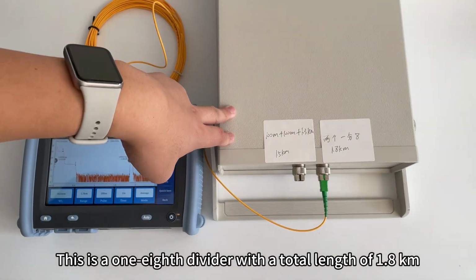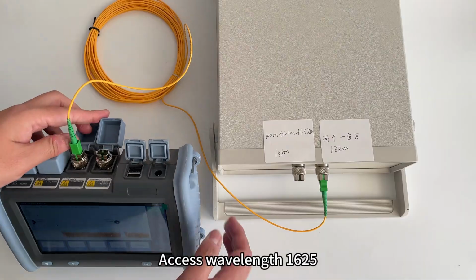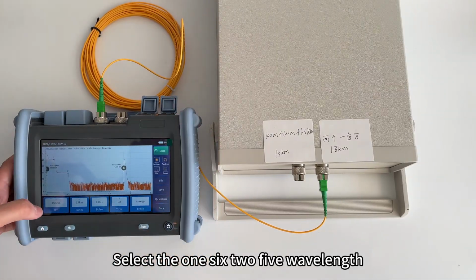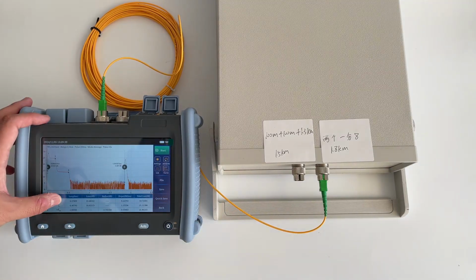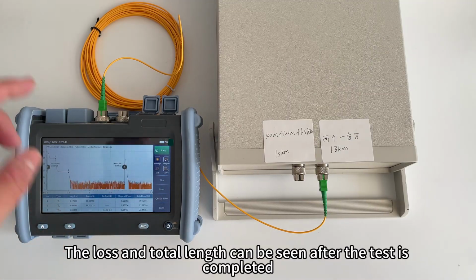This is a 1 to 8 splitter with a total length of 1.8 kilometers. Access wavelengths 1 to 5. Select the 1 to 5 wavelengths. Click to test. The loss and total length can be seen after the test is completed.